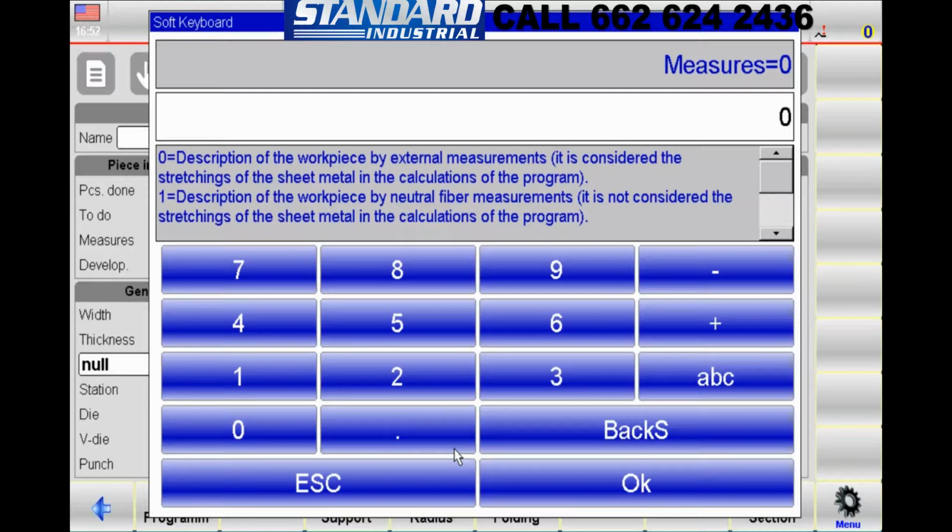And so these factors mean that producing the same bend length on the inside and the outside of the part actually requires different back gauge positions. So your CNC control must understand the perspective that's been used to design your part.